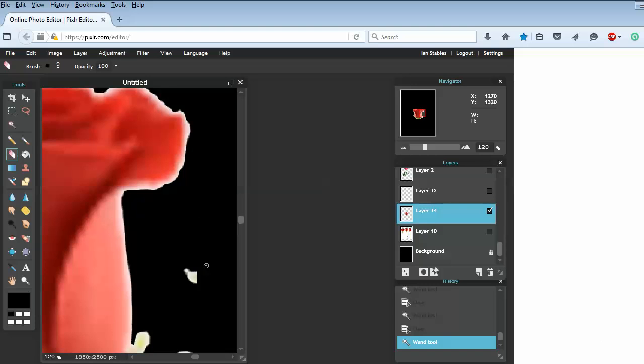Now if we were to want to rub this out, we could just simply hold the mouse button down and rub over that there. Okay, but when we're doing fine work, so say we want to come in here, just take that white edge off there. There's a bit of painstaking work here, but we simply move our mouse into position, and when we've got it on the bit we want to delete, we just simply click the left mouse button once, and so click and release. So that's just taking that little chunk and just simply go along, taking all the bits out that we wanted.